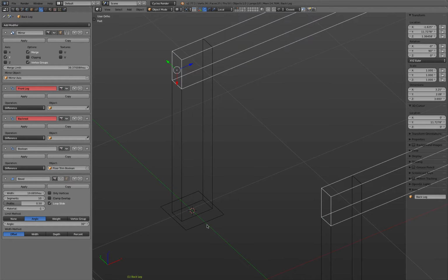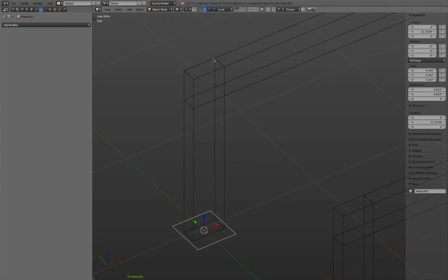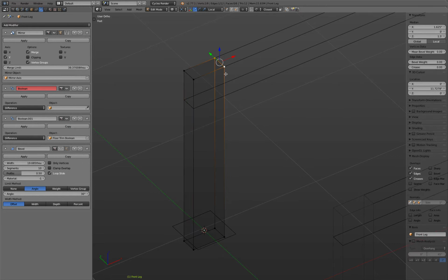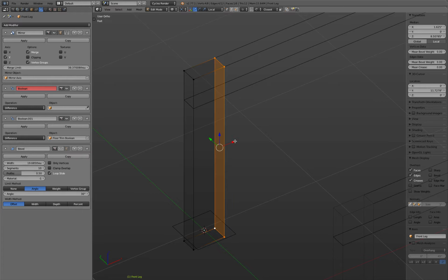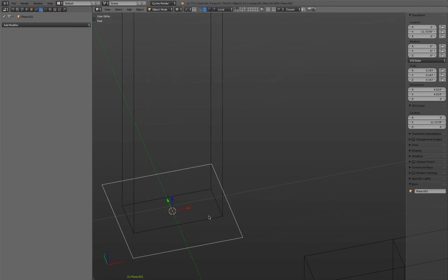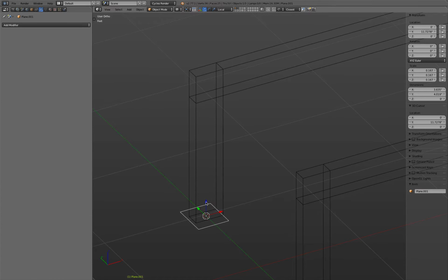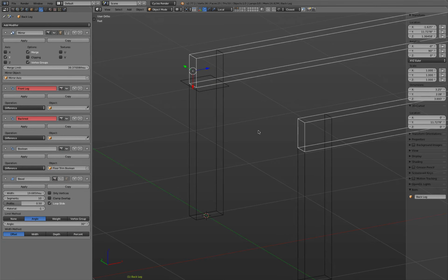I'll also turn the bevel off here, it's good to show the other object, because we want to create a volume that actually, I'm gonna explain this, starts from here and then grows this direction, and also, for example, grows up this way and grows this way. So this object, for example, we can go into edit mode. I have edge selected, move and snap to this edge. Perfect. And then we can move the whole plane up till it hits the bottom edge of this plank.